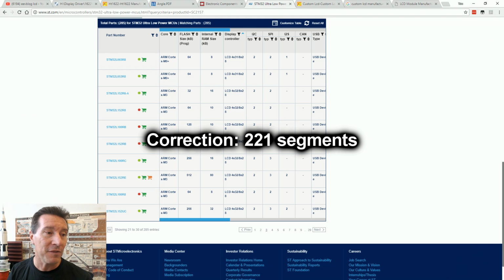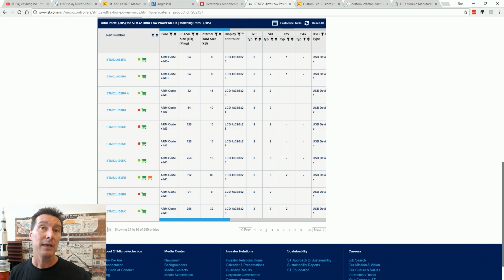But the problem with this is that it may force you into a much more expensive microcontroller because it's got 512K of memory, or it's got, you know, this and that. It's in a bigger package, it's got more pins, and it could double the cost of your chip. Your micro might be $1.50, for example, the one you were looking at using, and then when you search for one that has the built-in LCD as well, bigger package, whatever, it might force you into another model, and it could double the price to $3, for example. So you're effectively paying, in that example, $1.50 for the LCD controller.